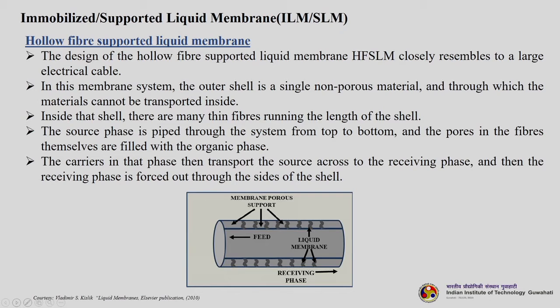So, here you can see the membranes, this is the membrane porous support. These are holes basically, inside which you have the liquid membrane impregnated. Feed is being passed from this side, and the receiving phase is outside. So, what will happen is the solute coming here will be transported through this liquid membrane phase and will go to the receiving phase. This is how it works.